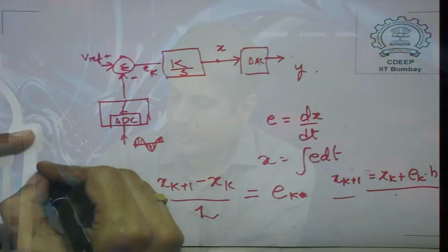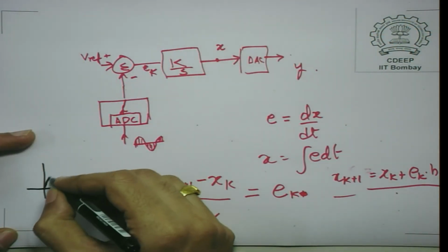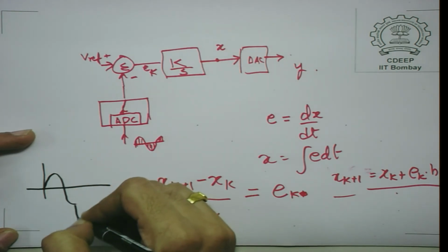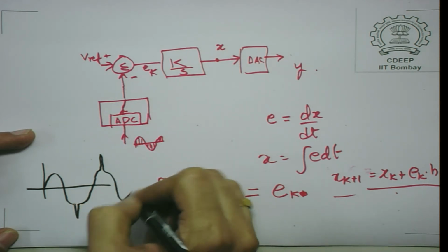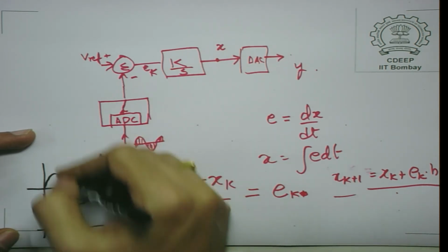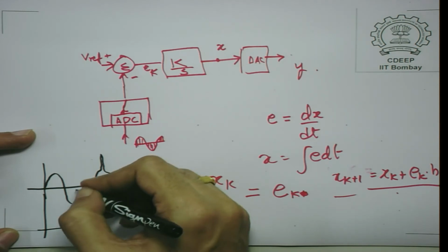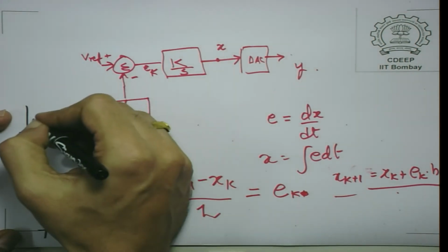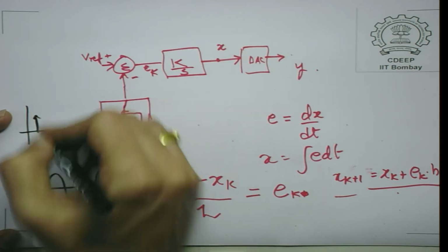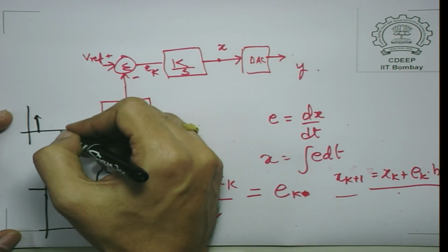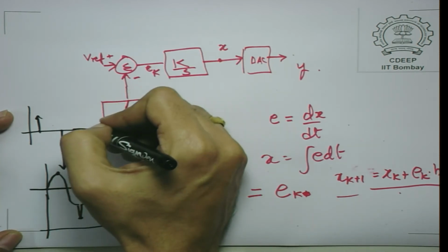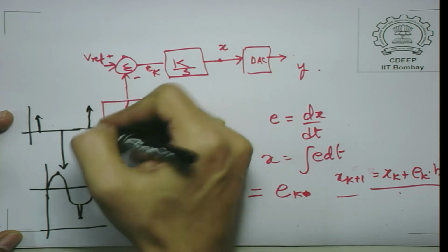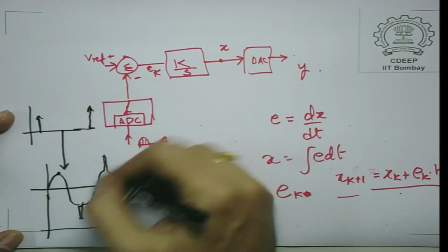For example, if this input here is supposed to be 50 hertz, but suppose it has some spikes, and you try to sample this at a low frequency, you may actually get, for example, you sampled it at this point, then at this point, and then at some other point here, which is slightly, you know, these may not be occurring exactly at the peak.